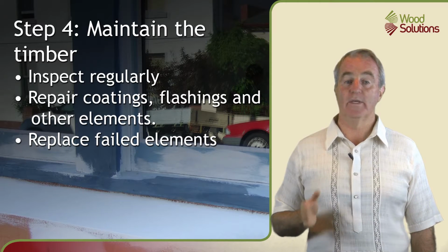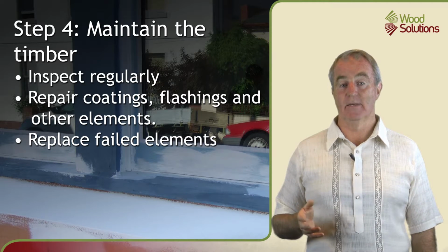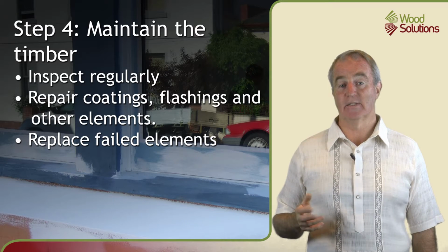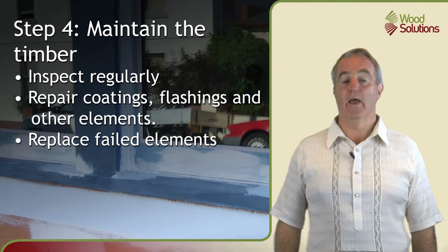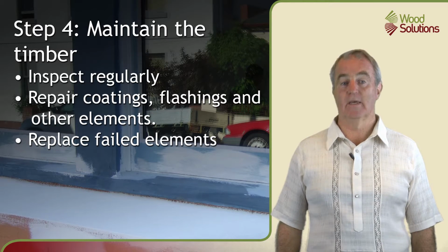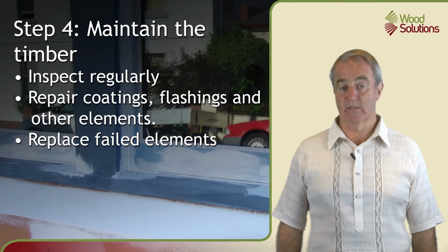Lastly, step 4 is to inspect and maintain the timber, its finishes, its flashings, and any protective treatment. This can range from recoating a surface to replenishing a preservative system.